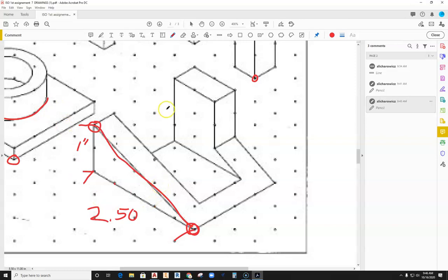So knowing that, any line that does not follow the isometric axes, and you can see I'm drawing on these axes right now, you cannot draw to a length. You can only connect the dots after you've drawn other lines that you can draw to length. So when you draw these lines, then you come back and you connect the dots from here to here. You can then create geometry for points. Go ahead and use your copy tool and copy from here to here and then trim what you don't need.